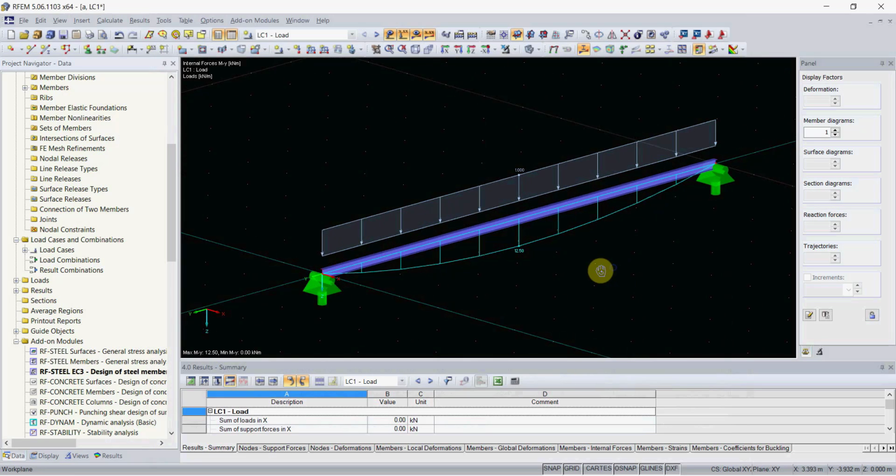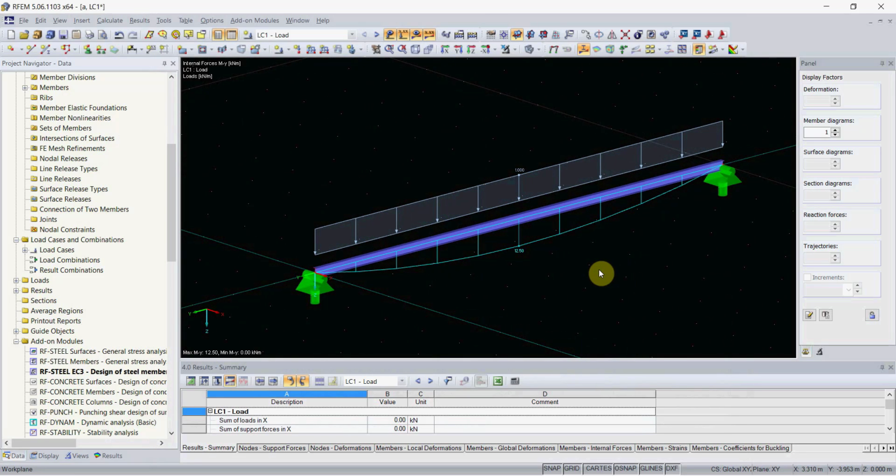This is of course not a numerical analysis, because equations were used. In order to calculate critical bending moment numerically, I need to have a model which does not use beam elements, but rather plate or shell elements.